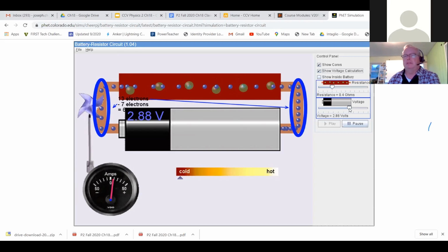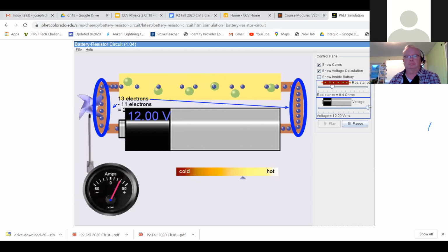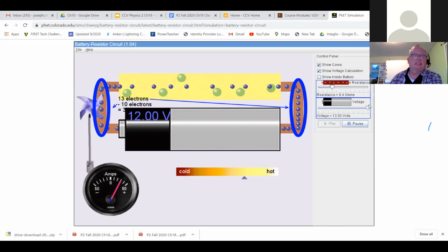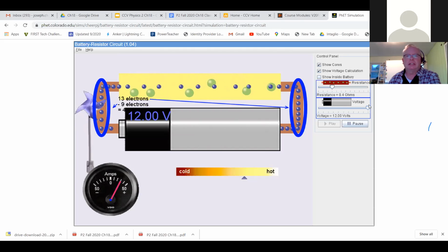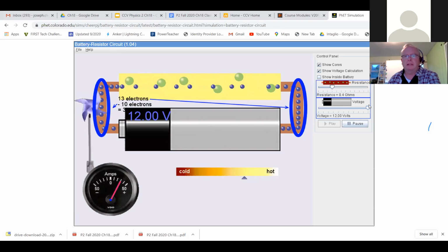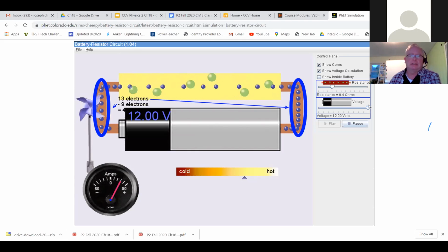All right, well, let's do the obvious. We'll turn up the voltage and see what happens. And you can see that the resistor is getting warm now. The conduction electrons inside the resistor are flowing okay, but they're having energy sharing collisions with some of the other molecules in the resistance. And when it gets hotter, they move back and forth faster, so it actually offers more resistance. Resistance increases as the device gets hotter.